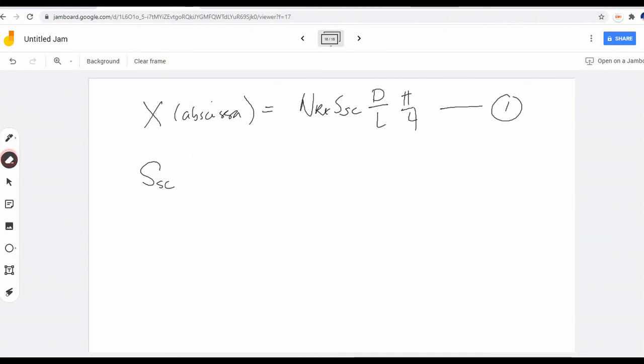By the way, the reason why I got this wrong is I wrote the capital letter S. So, this should be N. It's a dimensionless number, and this Schmidt number is equal to the mu over the rho times the molar diffusivity of naphthalene in air. Naphthalene is going to diffuse to air, so we need its molar diffusivity.